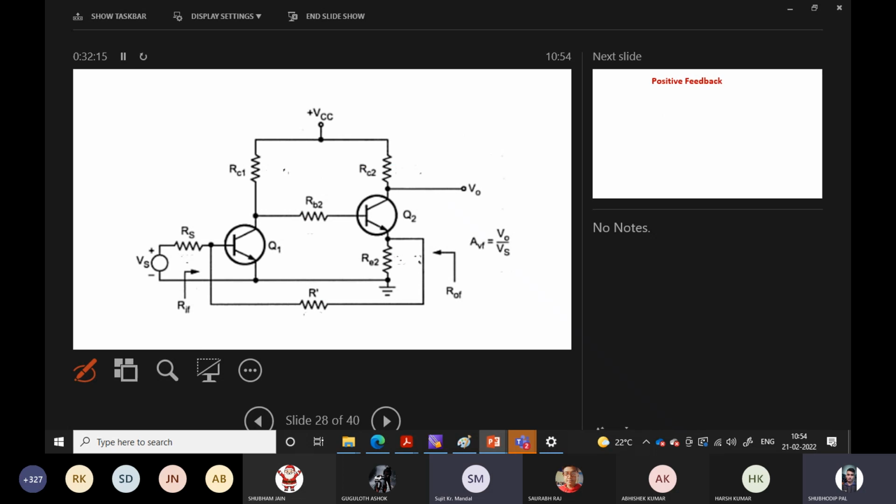Think about this also. For this case, what would the feedback type be? It is not taken from the output current; it is taken from here and connected to the input. So what type of feedback is this? Think about it with what we have discussed so far. It is your home task.